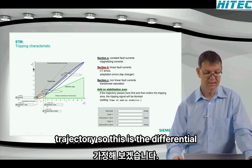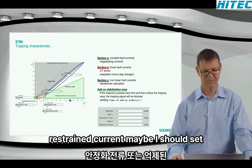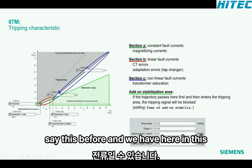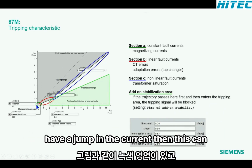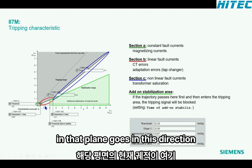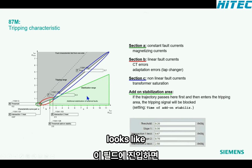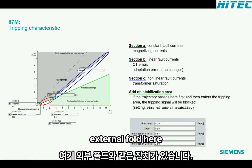So this is the differential current, this is the stabilizing current or restraint current. Maybe I should have said this before. And we have here in this green area a zone, and we know if we have a jump in the current, then this can be a fault. And if the current trajectory in that plane goes in this direction, so it enters this field, then it looks like, for the other devices, an external fault.